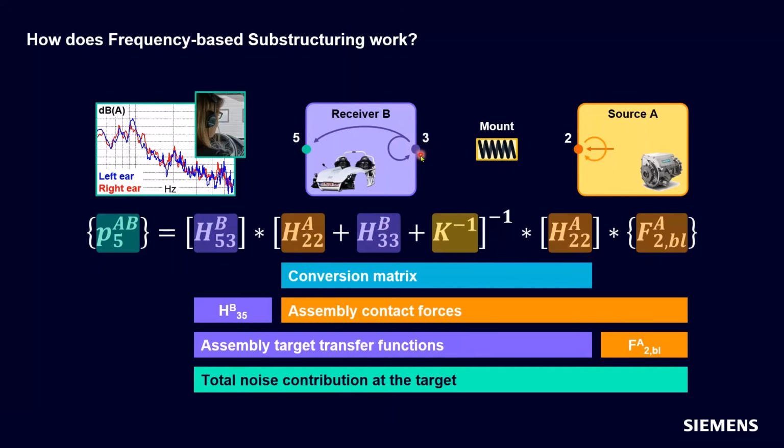So this is shown as a single connection point here, 0.3 and 0.2. Realistically, this could be 2, 3, 4 different connection points between the motor and body. We're just showing it as a single point. And so in traditional TPA, we take these assembly contact forces and see how they sum up to be our driver's ear, and then understand who's most responsible for that power transfer.